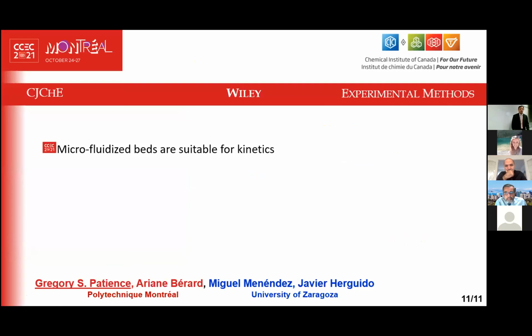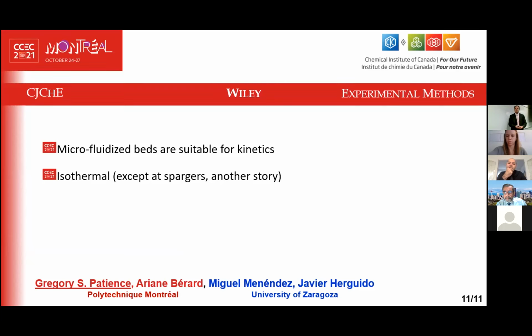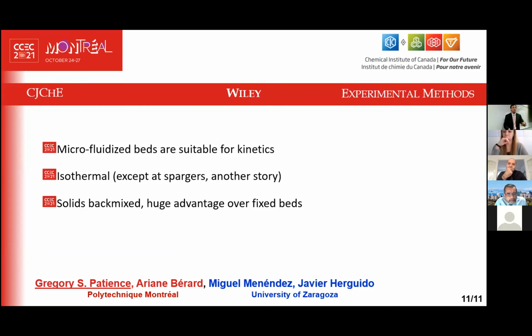So to conclude, microfluidized beds are suitable for kinetics. And again, this was a microfluidized bed. It wasn't a large fluidized bed with large bubbles and things like this. Now, the other advantage of fluidized beds is that they're approximately isothermal. And then solids are back mixed, which is a huge advantage over a fixed bed, because all the solids have the same oxidation state, the same deactivation rate, and the same carbon buildup. And is the gas in plug flow? We don't care if you're measuring the kinetics with 40% conversion. This sounds weird. Anyway, that was the conclusion.